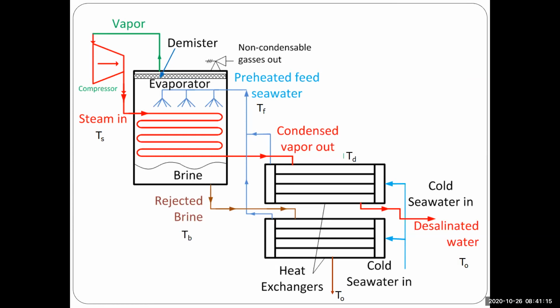Here we have no condensation. Accordingly, we just enter the value of m dot feed. This m dot feed will be distributed between these two heat exchangers so that it is heated up from T cooling water to T feed. And then the stream is taken to be entering to the evaporator where it will be sprayed.